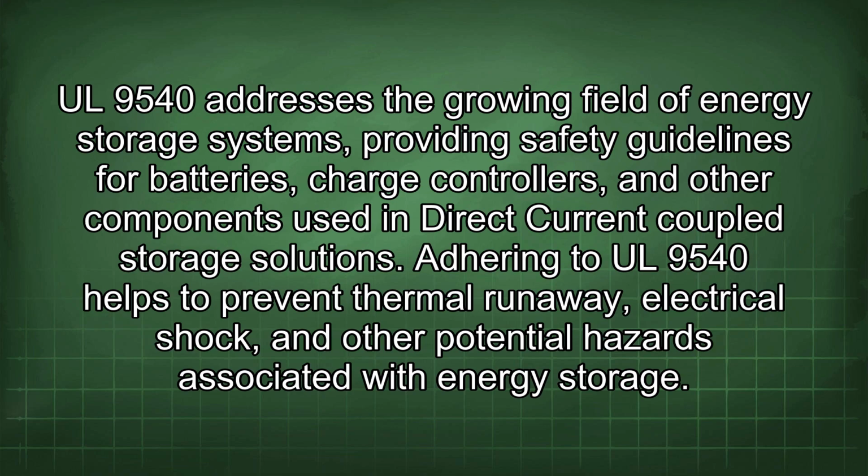UL 9540 addresses the growing field of energy storage systems, providing safety guidelines for batteries, charge controllers, and other components used in direct current coupled storage solutions. Adhering to UL 9540 helps to prevent thermal runaway, electrical shock, and other potential hazards associated with energy storage.